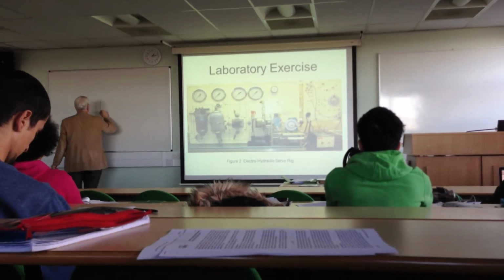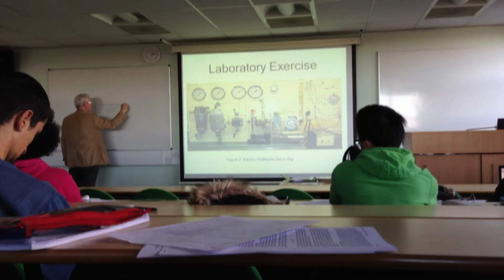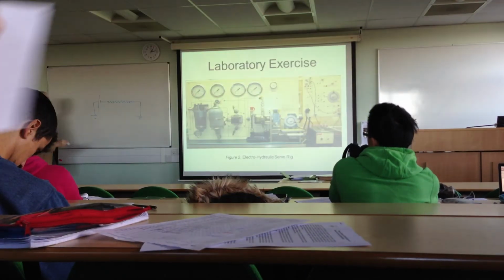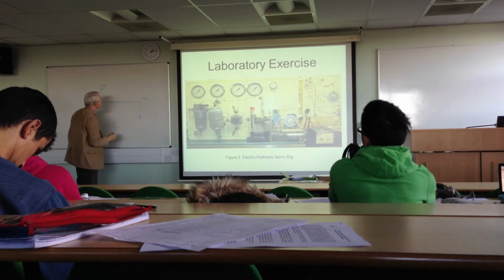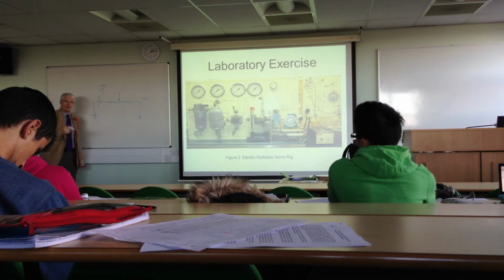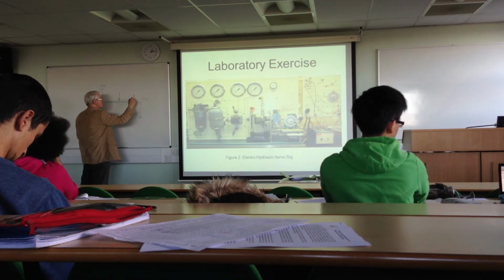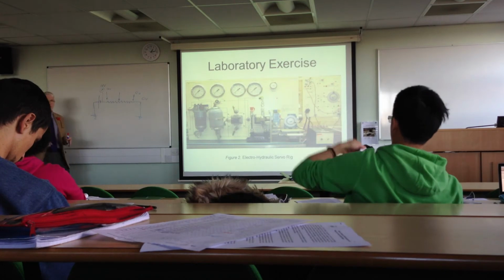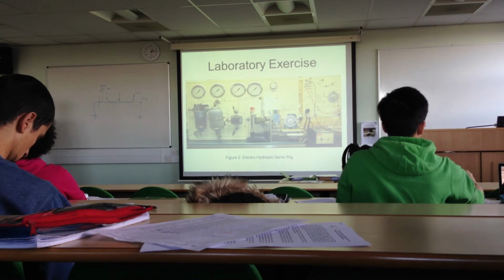If we look at electrical circuits, if we had a voltage on here, say 12 volts, and this is earth, so that's no volts there. If we were to have what's called a rheostat, in other words, we slide a contact along there, if it's over at this end, it reads 0 volts. If it's over at this end, it reads 12 volts. And anywhere in between, it reads an intermediate voltage. You're happy with that? Basic Ohm's law.